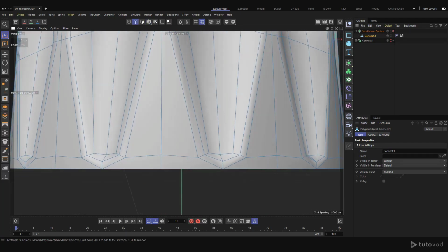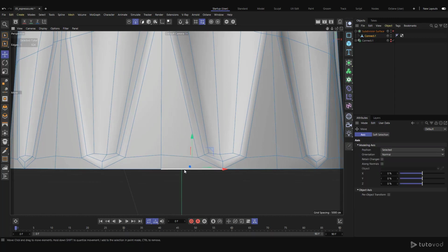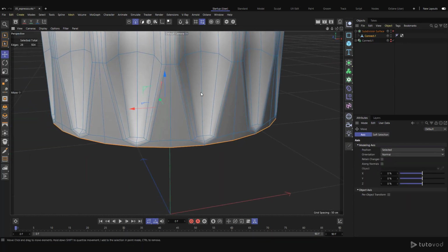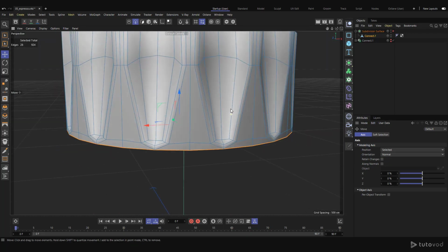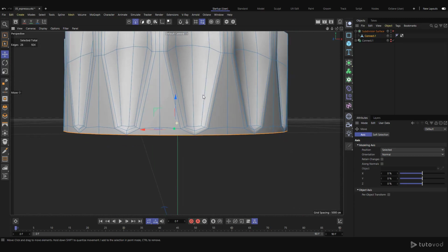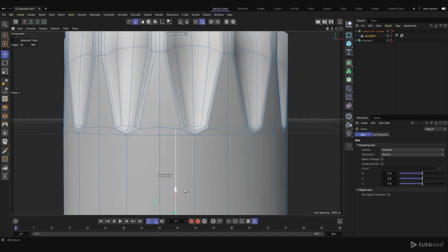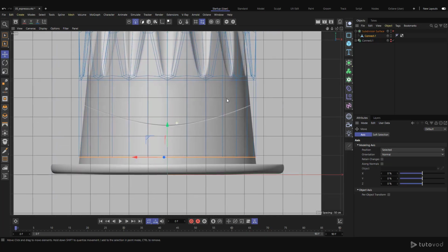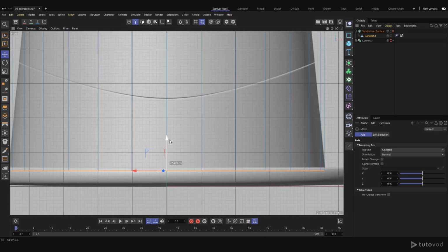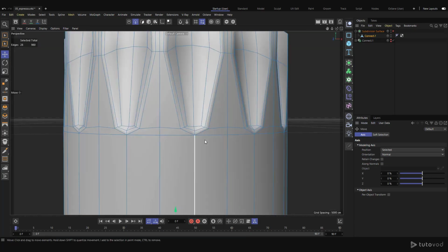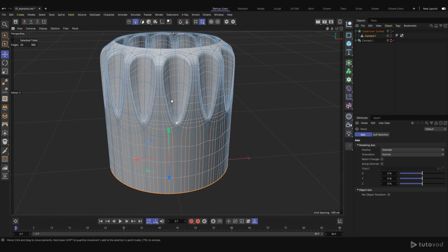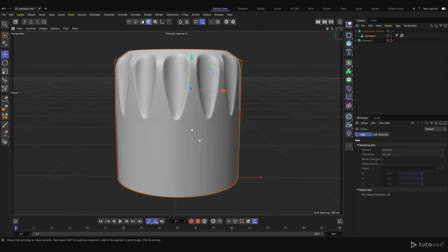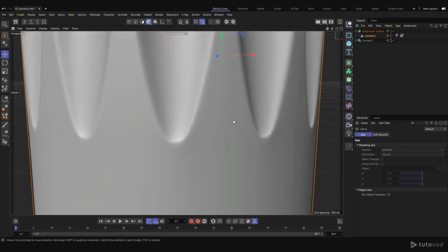So now what I'm going to do is select this line by double clicking on it. With any tool you can do this, and now I'm going to extrude it. So I'm going to press Ctrl and extrude it down like that and bring it here. So we get something like that. Let's turn on my subdivision surface, go to object mode and check if everything is okay.